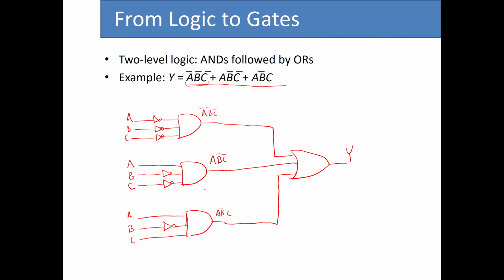So for example, we have several NOT gates that we can just easily eliminate if we basically reuse some of the signals that we create. So for example, whenever we use A, we can connect this one with this one, so they are basically the same thing, right? Or whenever we want to use B bar, we can all connect them to one signal and then eliminate 2 of these NOT gates, right?